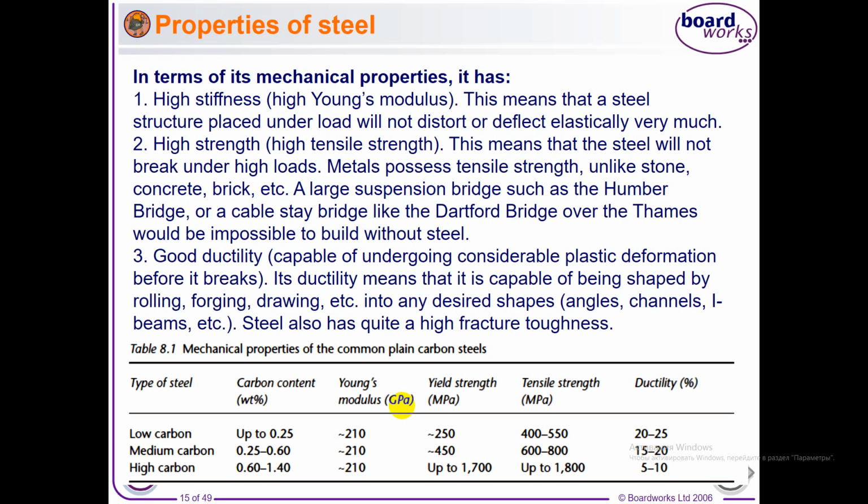We understand that steel is prone to wet corrosion. The reason is that it's a two-phase material. That is, its microstructure consists of two phases, ferrite and pearlite. You know that ferrite is virtually pure iron and pearlite a mixture of pure iron and iron carbide. Ferrite, being virtually pure iron, is single phase and so is much more corrosion resistant than steel.